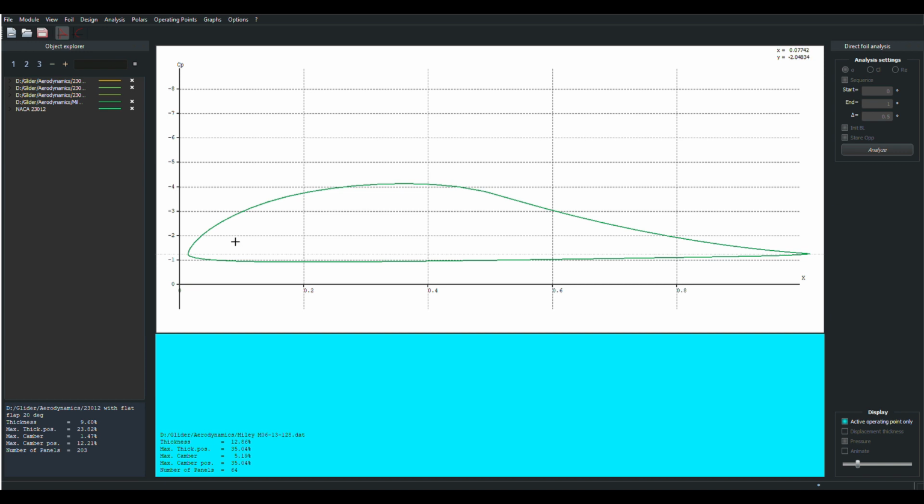And the design, as we got into numerical calculations, CFD, we'd say, oh, we can do a reverse design now. We can say, I want these flow conditions to exist. Show me what the airfoil looks like. And we started getting a bunch of airfoils like this. And this is similar to one that's on the Swift. And these airfoils generate really great CLs and low CDs. And they perform extremely well at low Reynolds numbers. They deliver this fantastic performance at low Reynolds numbers.